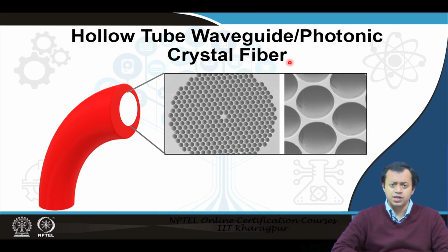I will be discussing in optical biosensors what photonic crystals are, but photonic crystals are the optical equivalent of semiconductors. In semiconductors, you have energy levels where an electron can be present, and energy levels where an electron cannot be present. Where electrons can be present are the conduction band and valence band. Where it cannot be present is the band gap. A photonic crystal produces a photonic band gap. They have energy levels where a photon cannot be present.